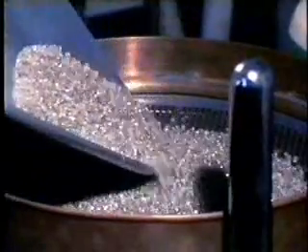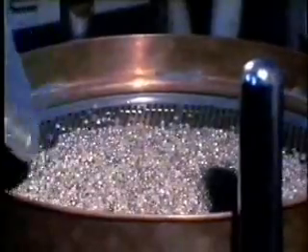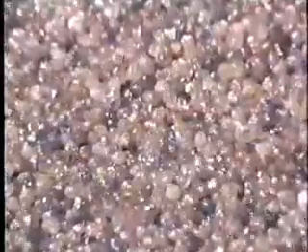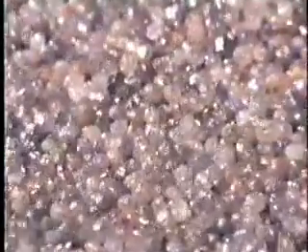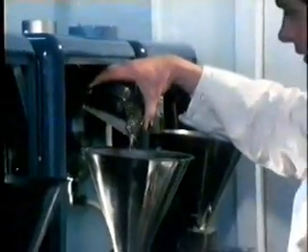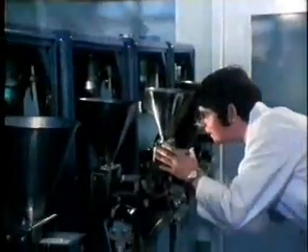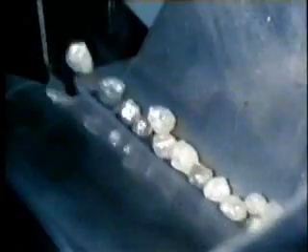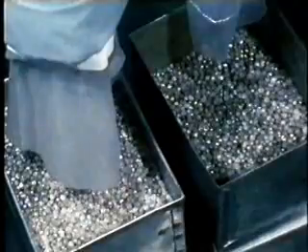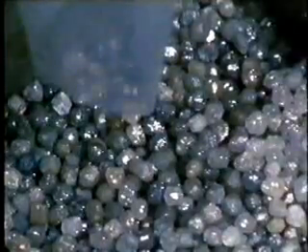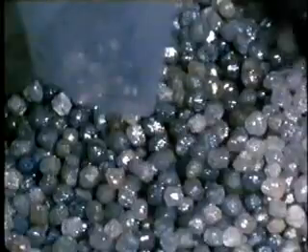The rough diamonds from the mine are first graded in a vibrating stack of different sized sieves. After sizing, the diamonds are separated for color. A photocell senses the depth of color in each diamond and grades accordingly. An air jet shows the darker ones into a color box. These are unacceptable as gemstones, but ideal for use in industry as cutting tool material.